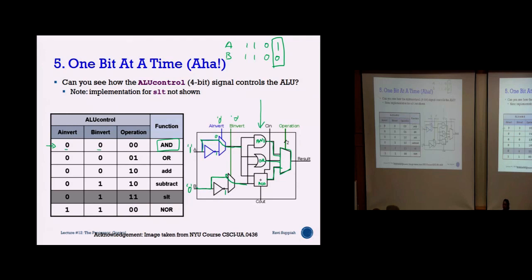This is a multiplexer with 2 selector input pins, correct? That means the possible values are 0 0, 0 1, 1 0, 1 1. If it was 0 0, the first line will go through, 0 1, the second line, 1 0, the third line. 1 1 is not used. 2 selector pins means I can have 4 inputs for a multiplexer. Since my operation here is 0 0, the first one, which is the AND, will go through, correct?